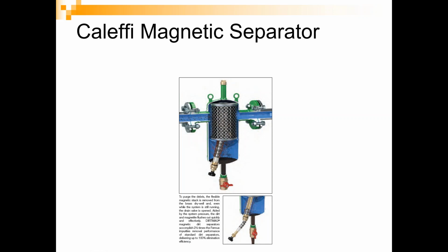Now, this becomes extremely important, especially when we're talking about high efficiency boilers. And when I show you the high efficiency pumps on the next slide, you're going to see why it becomes even more important for those as well, to make sure that we're doing magnetic separation in these systems to really pull out all that ferrous material. And it's really not a very big price add. It's fairly inexpensive, usually less than $1,000 price add into one of our air and dirt separators or one of our hydraulic separators.